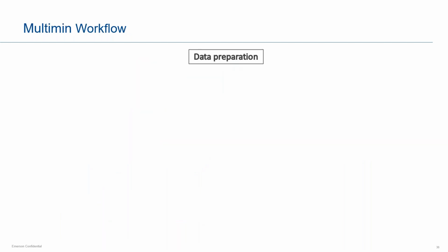So these are all about the theory parts. Now I'm going to discuss the Multimin workflow. As in any petrophysical interpretation, the first step is data preparation, where we do the QC and condition the logs. Once we have the conditioned logs, the next step in Multimin is to calculate the downhole mud properties. The feature in Geolog is known as precalc. In precalc, we calculate a continuous temperature and pressure curve. If we are using a water-based mud, we generate a resistivity of mud curve. At this stage we calculate the conductivity for use in the Multimin model.